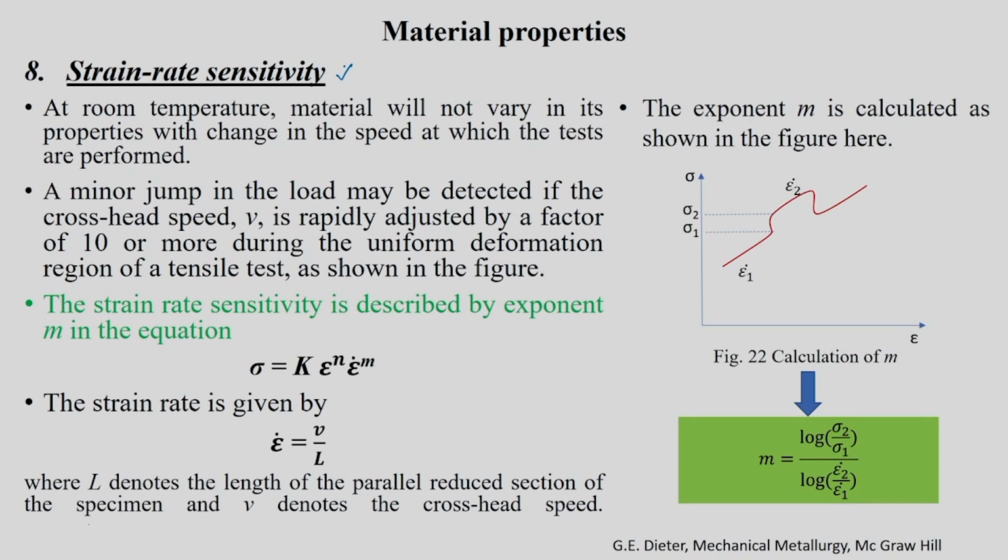Okay, so let us continue what we discussed in the previous class. Today we are going to discuss briefly strain rate sensitivity. We are going to continue with this important property which we can evaluate from the tensile test of a sheet. Strain rate sensitivity, as the name suggests, is a parameter that tells us how sensitive the material's deformation or flow stress is with respect to the strain rate.